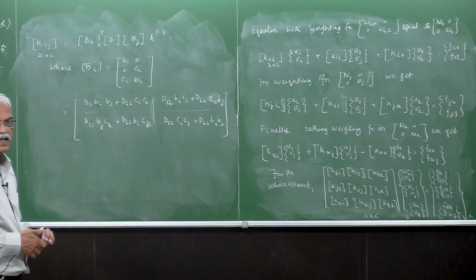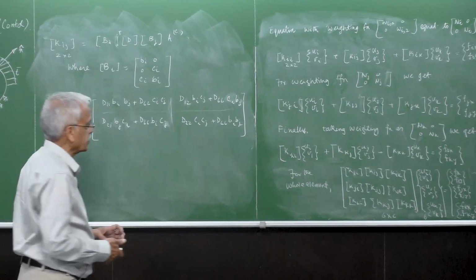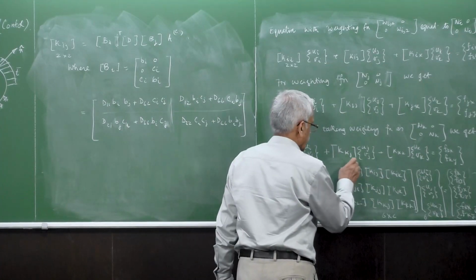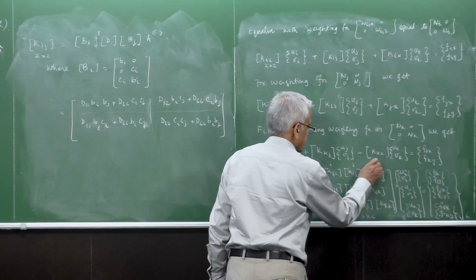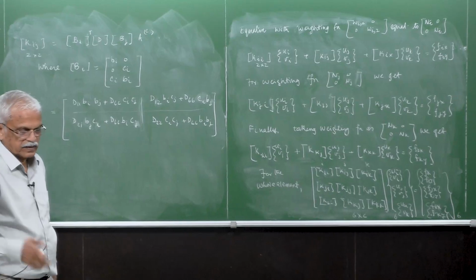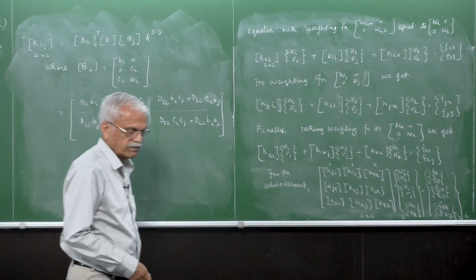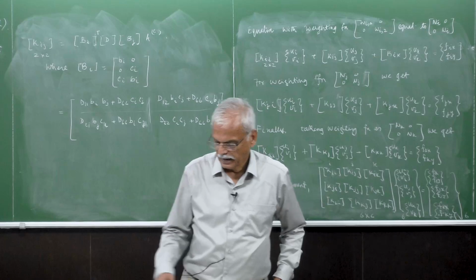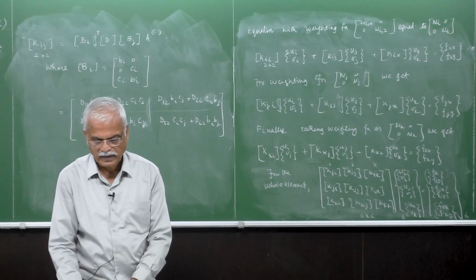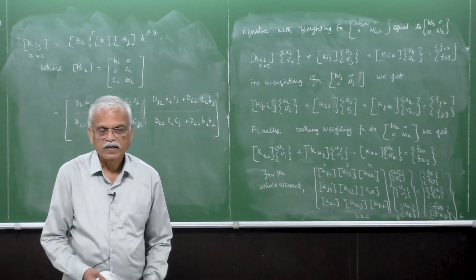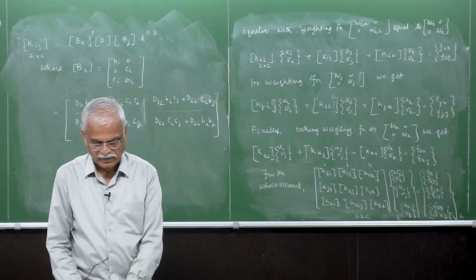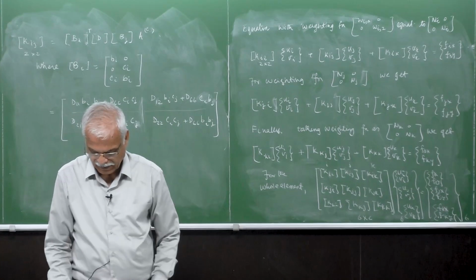So we have one element, and these go to the nodal degrees of freedom i, j, k. Each node has 2 degrees of freedom, and depending upon the node numbering, you have to assemble this, and then you have to apply the boundary conditions. We will come to that by giving a numerical example a little later.